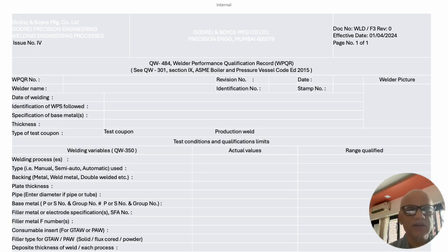So we can increase the thickness, range, or the weld metal deposited, and the backing details, whether it is metallic backing, weld metal backing, that means welding over welding, or the weld metal which is back chipped and re-welded. So the second side, when you are welding, has the first run as your weld backup, and then double welded. That means you have single V or double V, and sometimes you use ceramic backing or